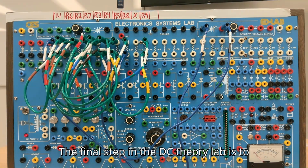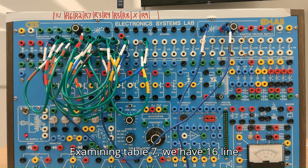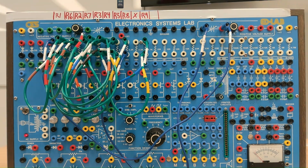The final step in the DC Theory Lab is to measure voltage throughout the circuit. Examining Table 7, we have 16 line items to complete. The first line item is to measure the source voltage. We're going to measure the source voltage to verify it's still at the 5 volts.